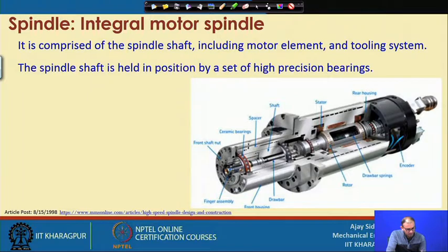Drawbar is used to actually remove and add, couple your cutting tool here at this location, because drawbar has one type of plunging mechanism. By that plunging mechanism, when it is moving outward, at that time it will open the jaw of this particular assembly whatever you are using here, and when it is drawing back, at that time it will actually grip whatever things you are adding. Mostly it is a cutting tool.